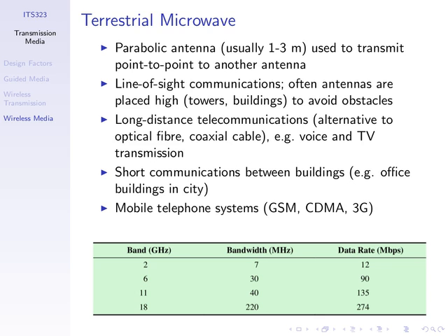Our signal is not sent along the ground, it's slightly above the ground, so we have a transmitter and receiver at approximately ground level. Such systems are normally point-to-point using dish-shaped, parabolic antennas, where we have one transmitter transmitting to a receiver in a point-to-point configuration. We have some tower with our transmit antenna and our receive antenna.